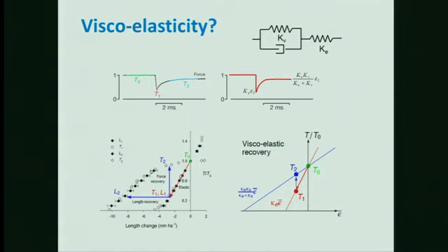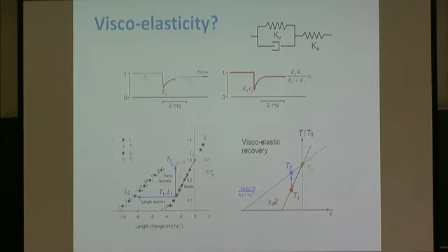However, if you look at the force as a function of applied stretch, suppose you shorten this system, first this spring would respond, you have elastic behavior, then at a longer time when this Kelvin type viscoelasticity would get into action, there would be a partial recovery, but again, then you will see the smaller stiffness of the parallel connection of these two springs,